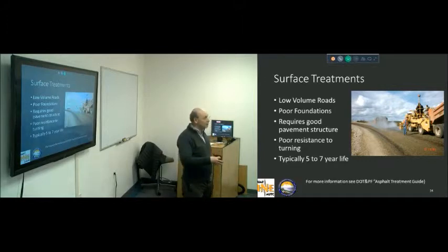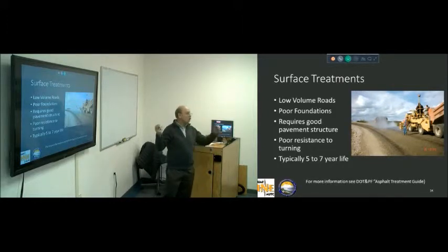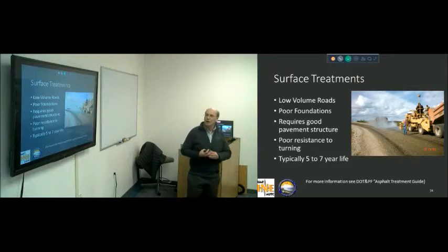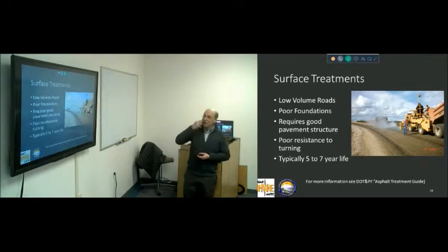Don't think because you're going to use a chip seal that you can get away. Actually, it takes a better pavement structure than asphalt concrete, because it has no strength. So if you don't put in a good pavement structure in there, it's going to break up very, very quickly, and you're going to wonder why. You really want to make sure. If anything, you probably need a better pavement structure on surface treatments than you do hot mix.